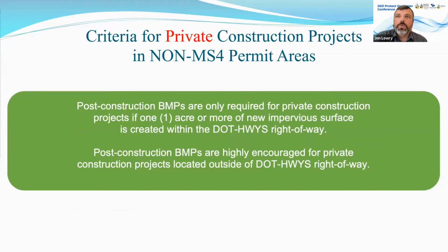So, criteria for private construction projects in non-MS4 permit areas. Basically, they're only required for private construction projects if 1 acre or more of new impervious surface is created within the DOT highways right of way. If you're in a non-MS4 permit area and you're doing a private project completely outside of DOT highways right of way, it's only encouraged, not required, that you implement post-construction BMPs. Okay, next slide, please.